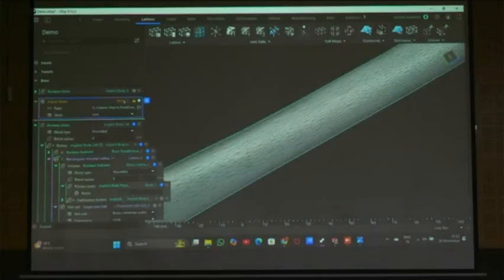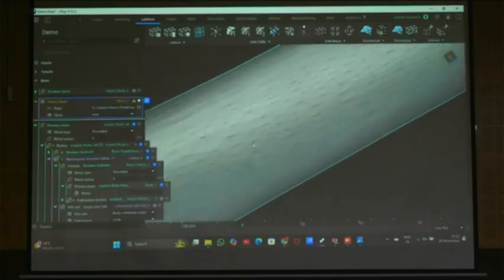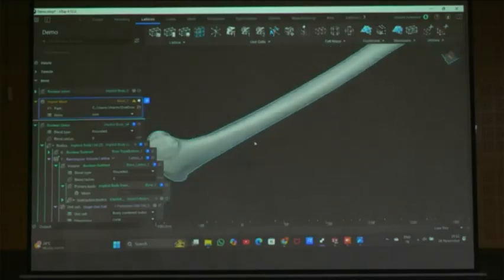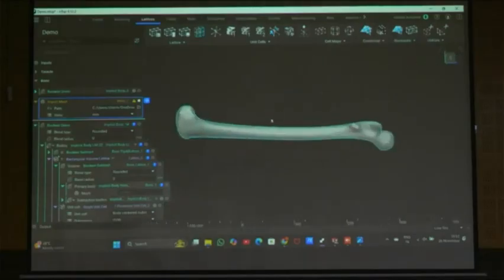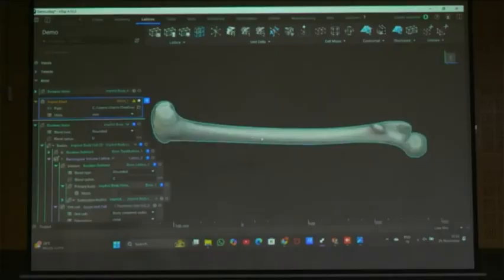So this is the meshed body. So the tessellation looks like this, right? My objective is to apply a lattice in between. Previously the same thing was there, with the tensile body: left, right, middle. But this is the STL body. Previously we designed the CAD body and separated it in the CAD software itself. But here in nTop, this is the STL body, and we cannot do the separation in SolidWorks or CAD software, so we are using nTop here.